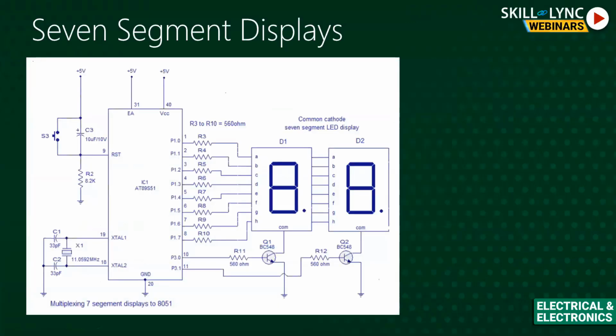Let's consider one more case, where I have multiple displays, because definitely we need to connect multiple 7 segment displays whenever we are using them. In that case, I need to first do the individual selection of the segment, and then load the value. Here I will have two dedicated pins used for the selection. Using that, I will select and load the value, select and load the value.